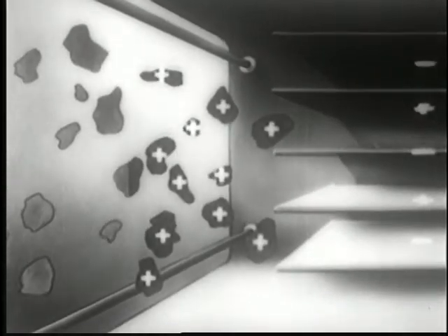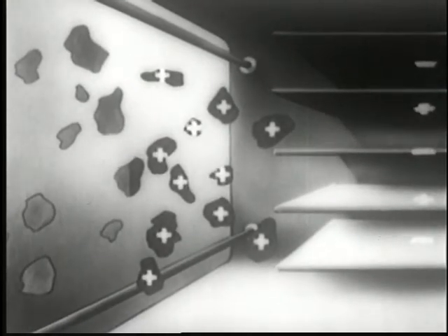As incoming air passes through the field of these wires, each particle of dirt receives a positive electrostatic charge. When the positively charged particle reaches the collector chamber, it's attracted to and deposited on negative plates. In this way, air is cleaned so thoroughly that dirt particles down to a quarter millionth of an inch are removed. This is a vital advantage today, not only in homes and public buildings, but in industrial plants of all kinds.